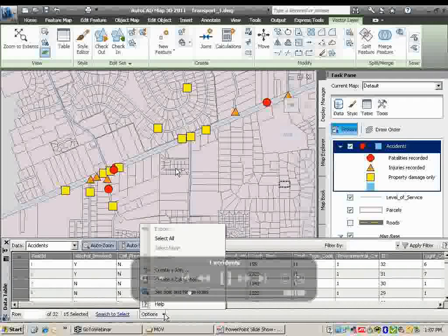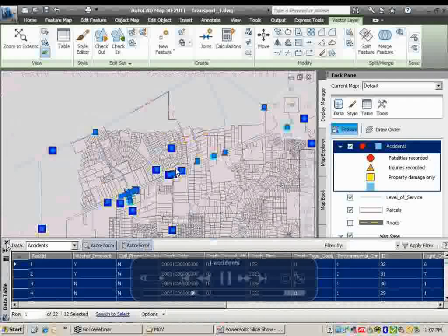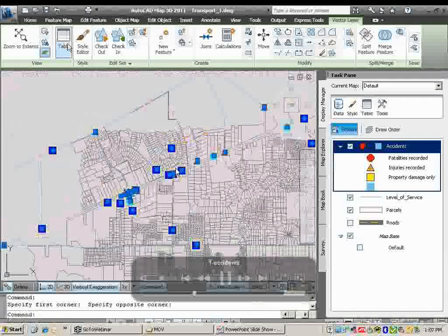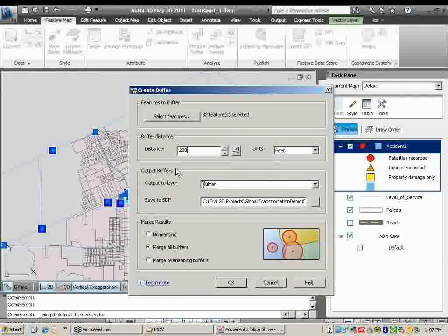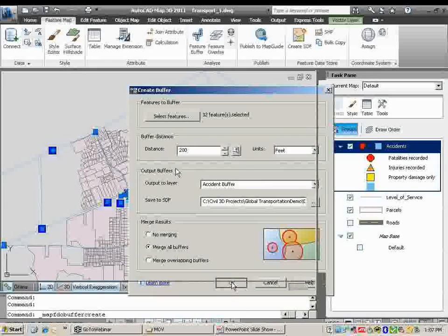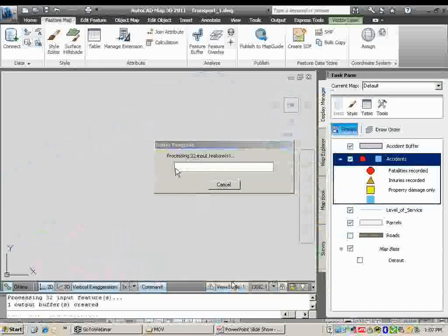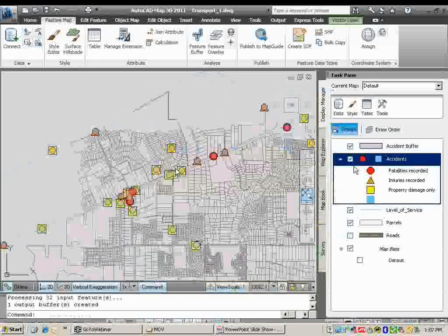Then what we're doing here is selecting this information, and we're going to turn around and basically what's called buffer the data. Because what we want to do is mathematics based on where an intersection is or wherever their accidents are. We can have a classical intersection where we've had 20 accidents in the last year or whatever summation time you want. And what we're doing right here is automatically creating an accident buffer around these areas. So that puts a perimeter around the accident spot.